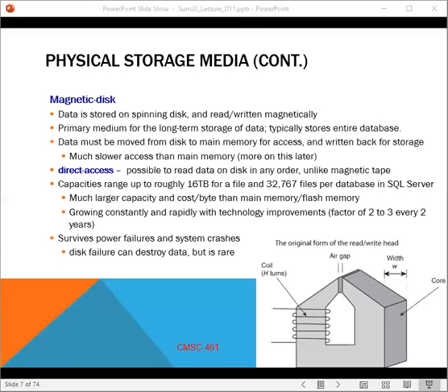Again, constructing read-write heads is difficult because of the complex interacting requirements of the recording system. The air gap has to be really narrow. If it's large, the area of magnetism is also large, and that reduces the number of bits that we can store on a device. So instead of having 1 terabyte on a disk, we'd have 5 megabytes as we loosen all the elements we see in the various components of the hard disk systems, including that air gap in the read-write head.